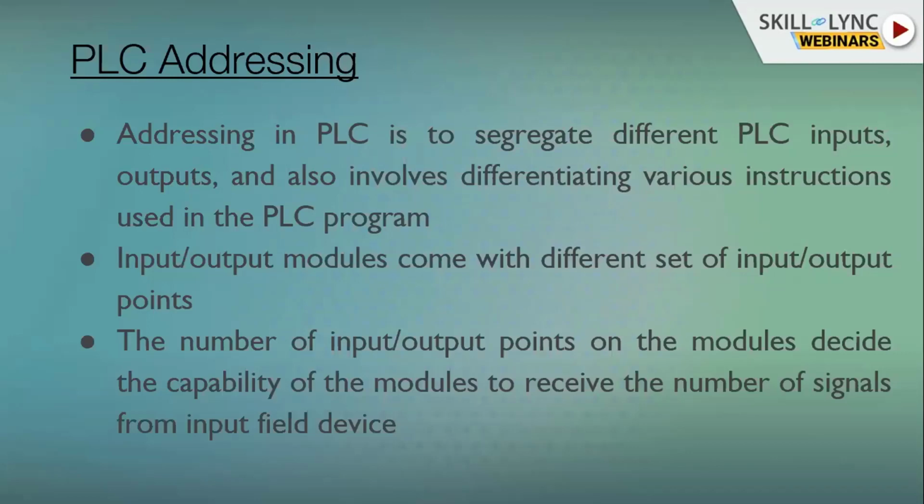When they are addressed, they keep in mind to have the information of the location of that input in the PLC system, whether it is input or output, and which number of point in the PLC input modules or output modules. Those informations are carried by the address of that element.